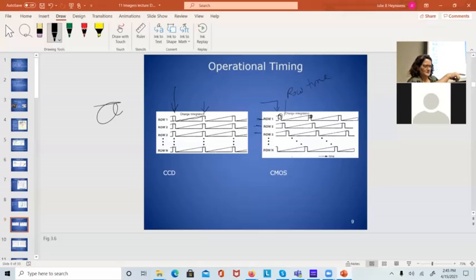when we get to interleaving too, because this was kind of a real problem in the early cameras, early video cameras. This integration time is variable, and you can set it. If we set it to our minimum integration time, we could see the fan standing still. If we set it at a really long integration time, we could take a picture in a dark room that you normally just can't see anything in.